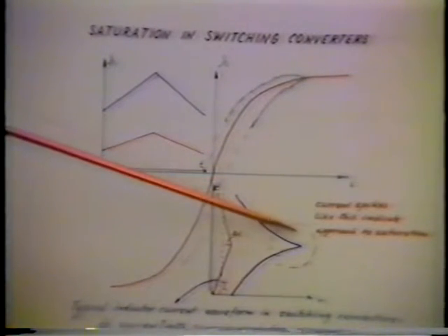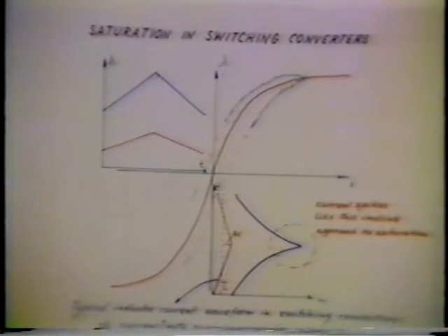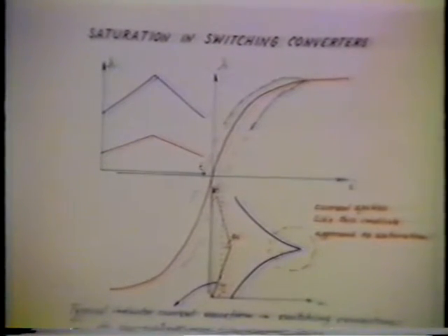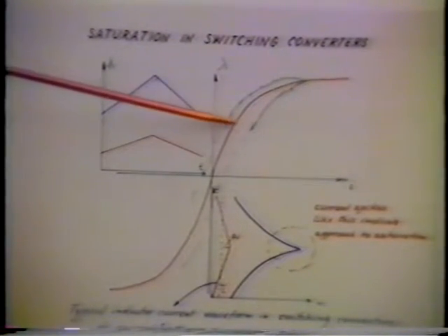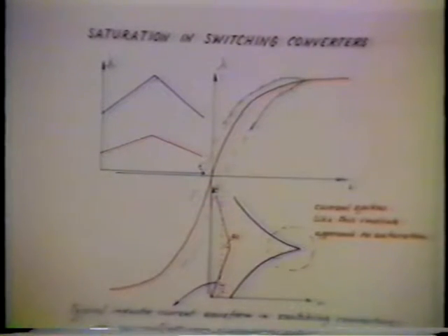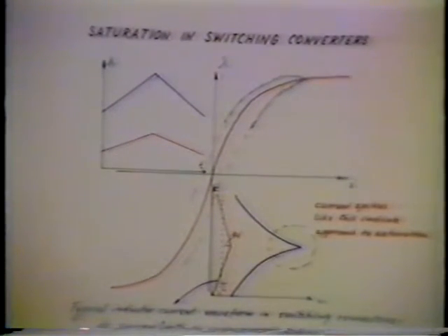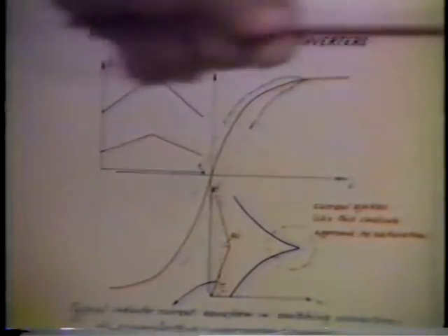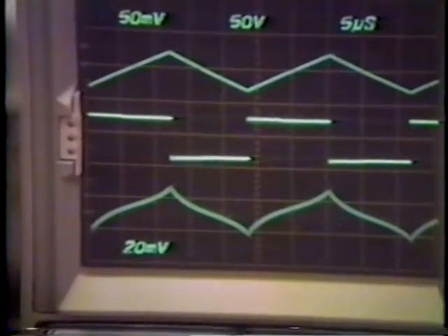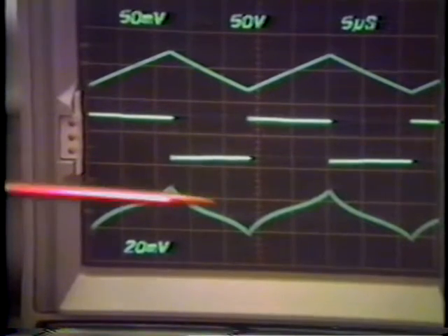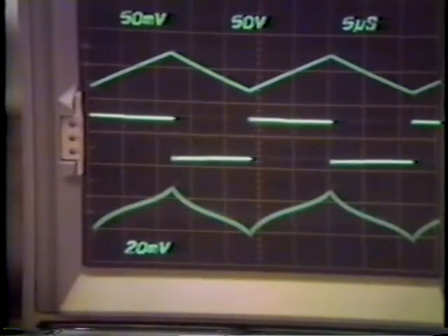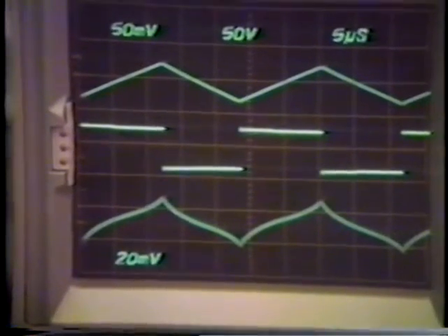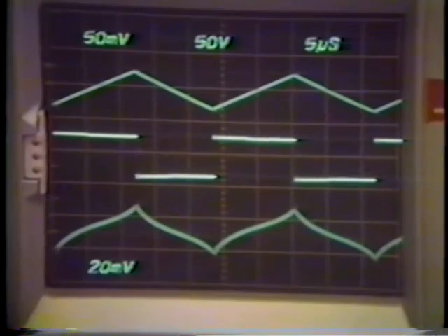Therefore, the two parts of the curves will no longer be symmetrical, and the asymmetry is actually due to the finite width of the BH loop, and it is in fact reflecting the presence of the hysteresis loss current in the device. We can actually observe that on the scope, if you look at the 50% driven converter, that the outgoing and downgoing curves are not identical. And as we said, the asymmetry is due to the finite width of the BH loop.